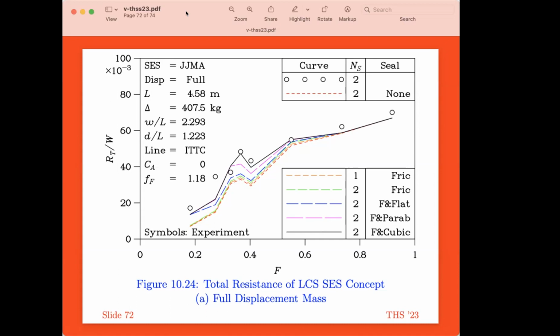And we use interceptors in the stern, which is really effective in providing the kind of lift force in the stern to provide the correct running trim at high Froude numbers. Okay, I haven't done the calculations myself, but I'm thinking on the fly at the moment that the optimum trim that you're talking about is obtained by minimizing the interference of the skirts.